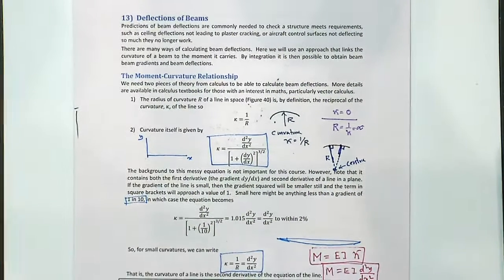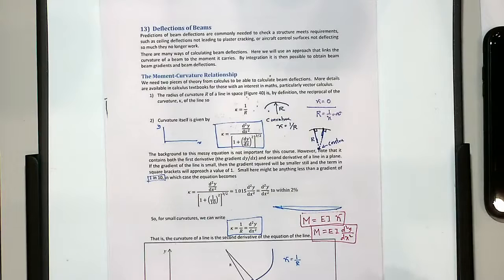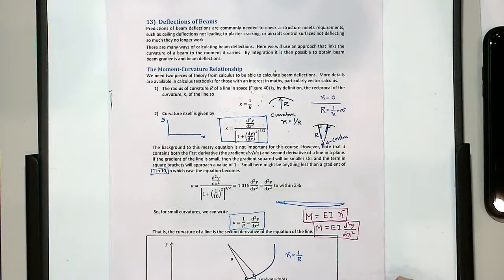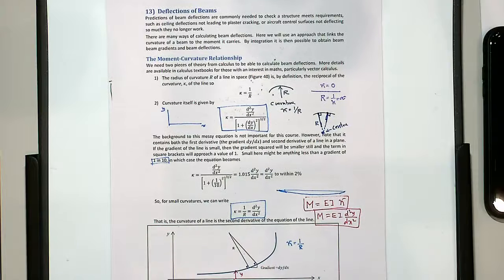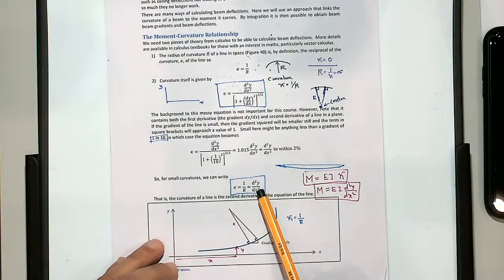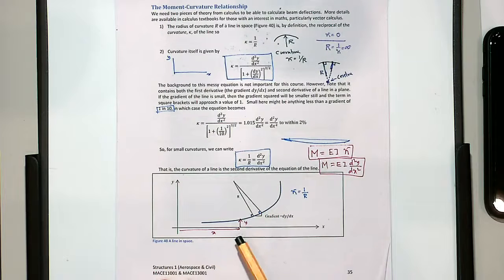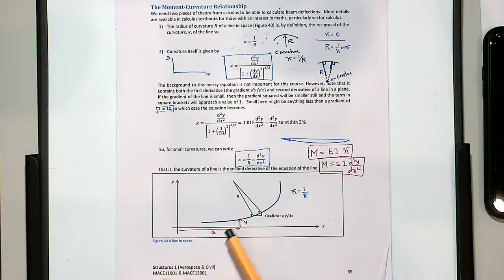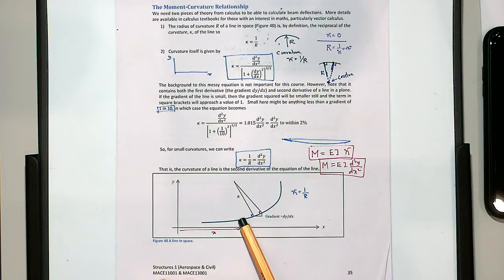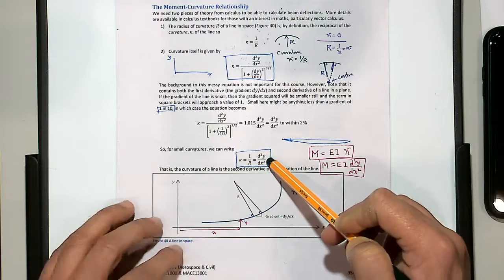So last Monday we started looking at calculations for deflection of beams. Just to bring your memories back, we used these expressions: curvature is d2y/dx2 if a curve is x versus y, where y is the deflection at a distance x. So y is the deflection of this beam, then the curvature is approximated as d2y/dx2.